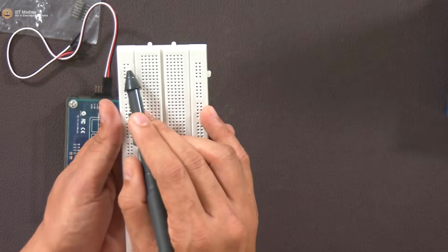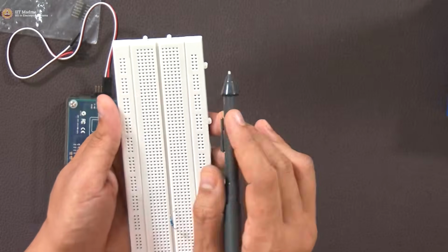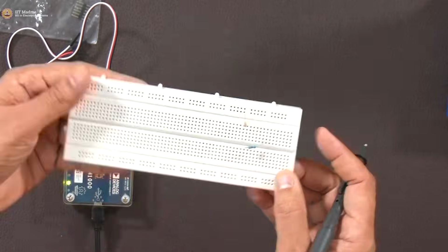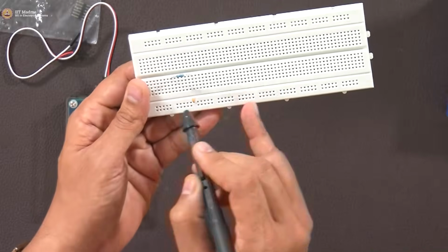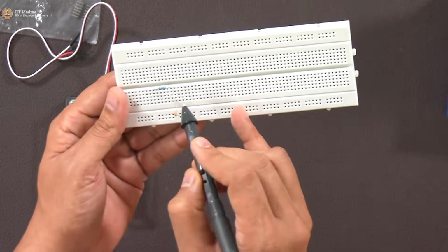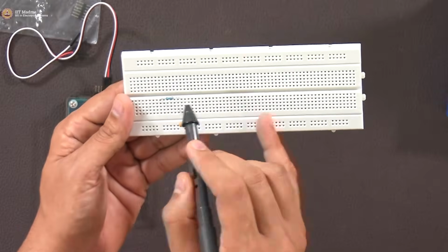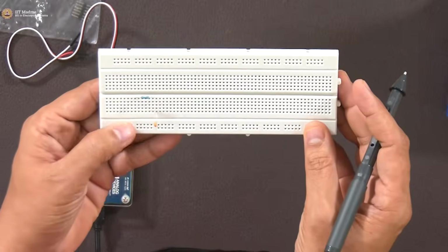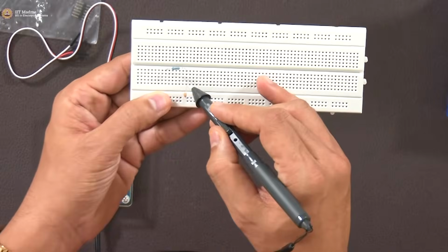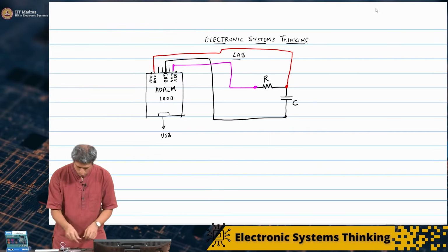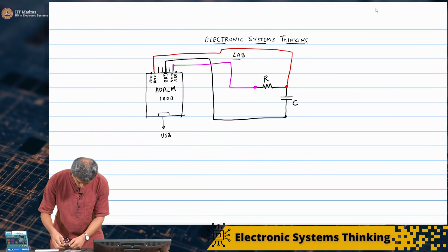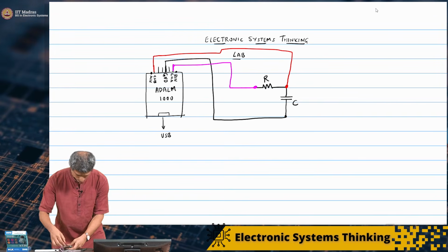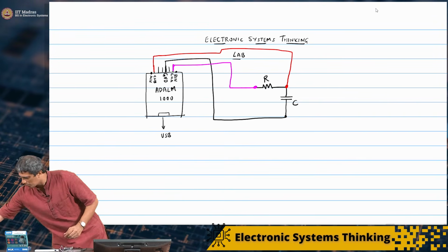So what we have done is connected the capacitor between one of these points and the resistor point. Remember, we are connecting this capacitor to A and the resistor to E. Now all of them are shorted, so it does not matter there, and I have connected the capacitor to the ground, right. So now I will take this connection out, okay.